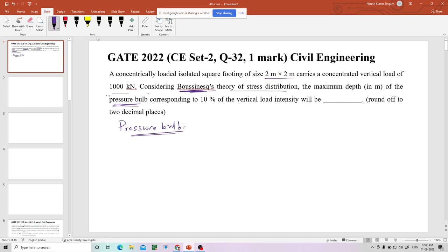See, whenever there is a load on the ground surface, so this is the ground level, you can say, whenever there is a load or any pressure, an areal load, there will be an increment in the stress in the ground. There is already an in situ stress at this point. Let us say this is H and unit weight is gamma. Gamma into H is the in situ stress. When there is a Q, this Q will increase the pressure in the ground. That increment in the pressure is denoted by delta sigma.